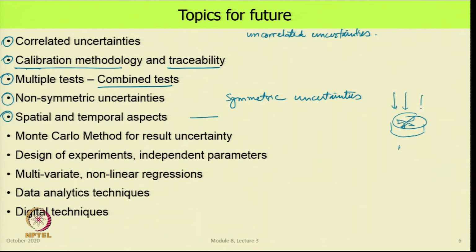So, this works fine if the velocity coming all over the anemometer is the same. If it is uniform over the face, this is a good instrument. But what if this velocity were larger, then this is smaller, this is even smaller, this is much smaller? Then what does the reading of the instrument mean?